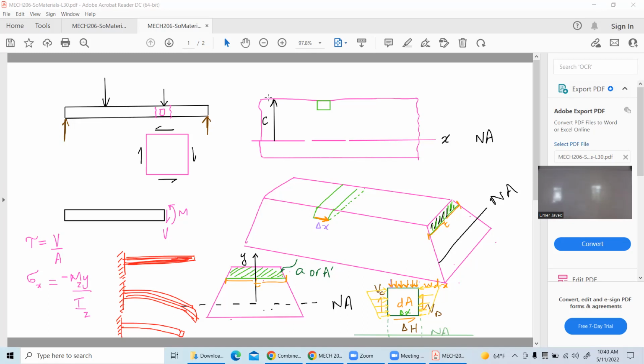See, if I hold it like this, you see all the pages. So you technically have shear between the layers of the pages, right? That's why you see this kind of a dip. Now, if I just clamp it from here, in fact, if I had a clamp, I could have shown you, and then I would have hung it, you would see that this thing will not even deflect like this. So you can see that there is definitely a shearing between these pages.